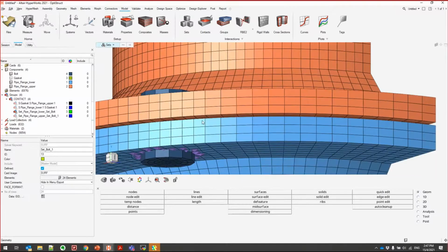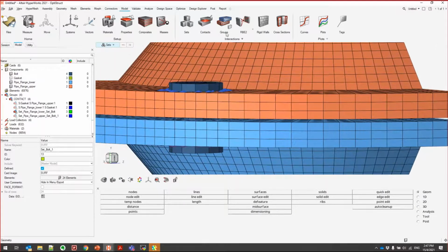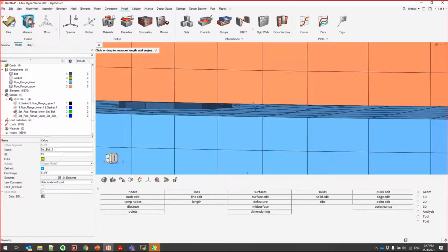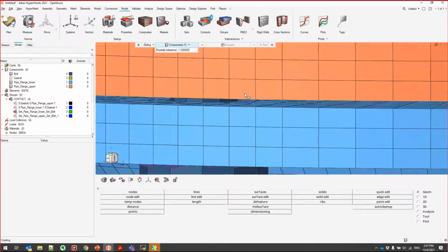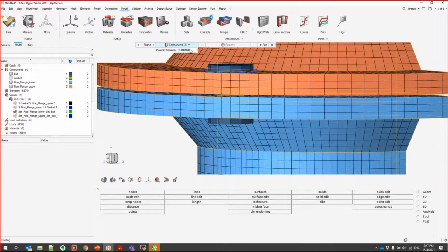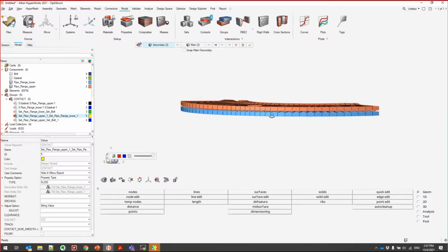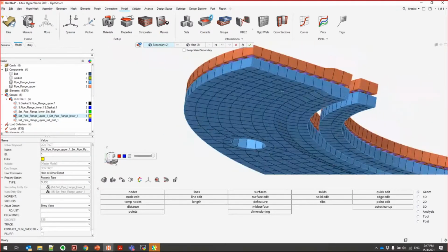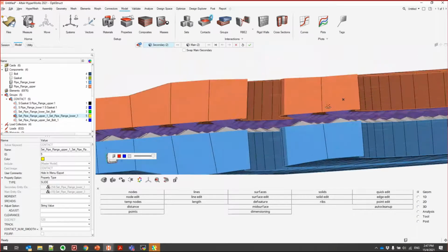Okay. So this one, it didn't manage to capture, maybe because I put proximity to be 1.0. So if I measure here, it's actually 2 lah. So let's say if I now try, select the 2 components, put in, let's say, 2.5 proximity, and between the 2 components and find, it should be able to create that contact. Yep. So these are all the contact areas lah.